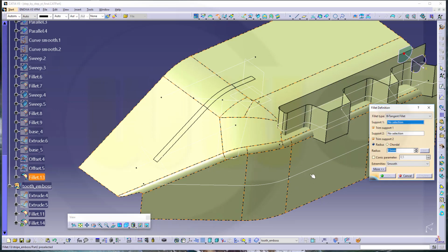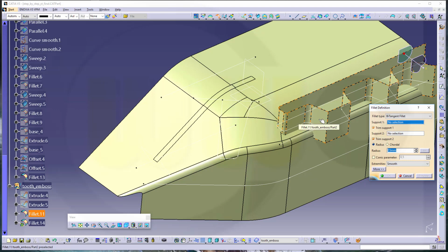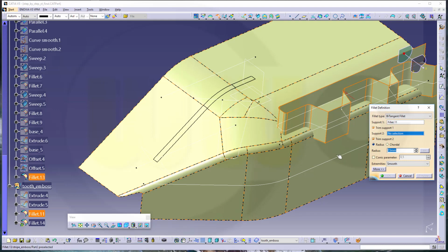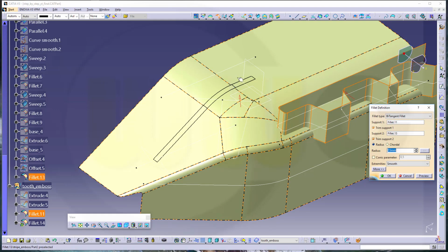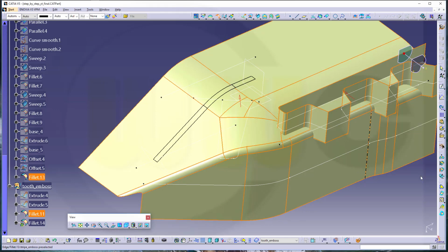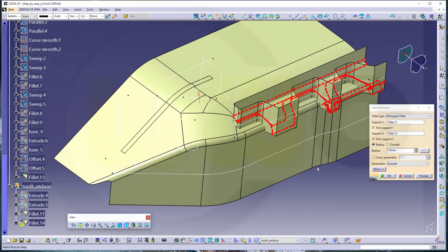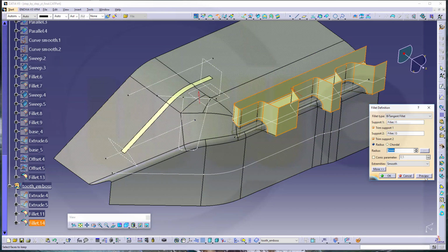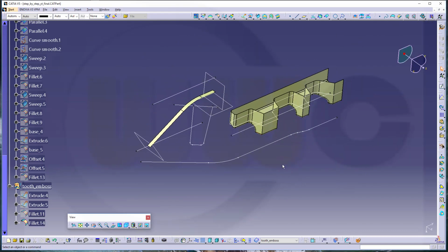And let's go for a shape fillet. And I want to do it between this one, I think that's this direction, and that one, and that should show up. Preview. That doesn't work. Maybe one of those arrows is wrong. No, it's not wrong, but the radius is too big. It should be 5, of course. Let's try another preview. This looks promising, and confirm. Nice.